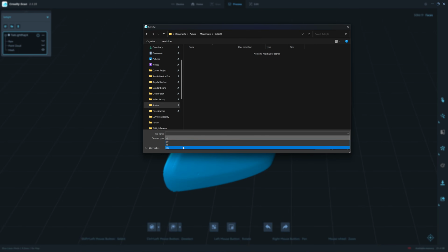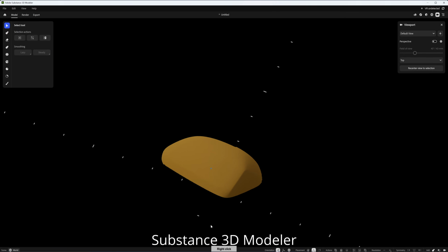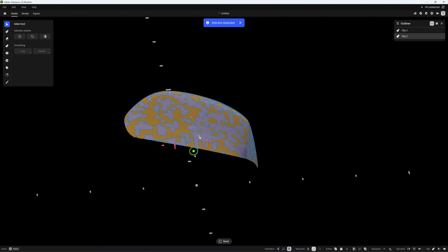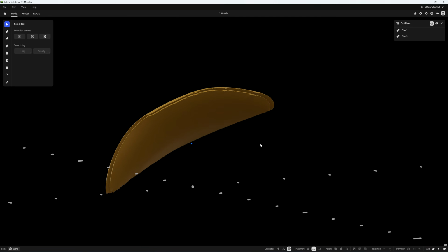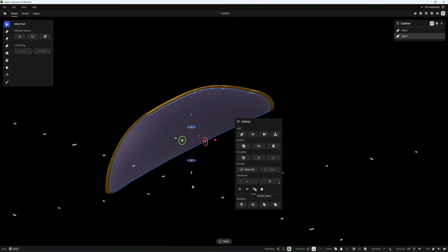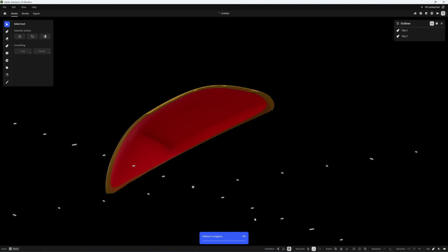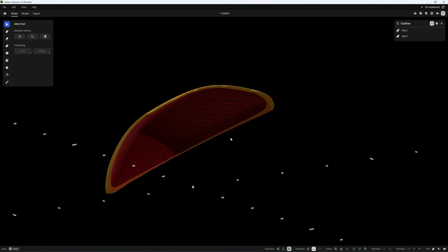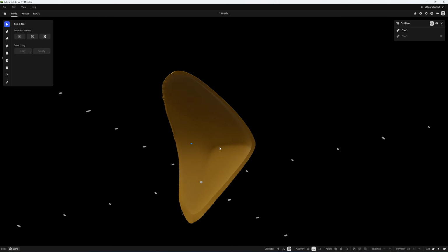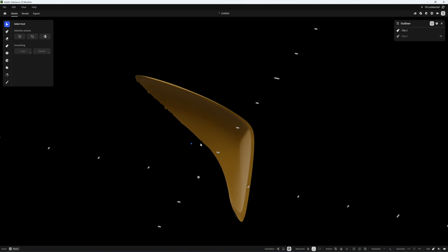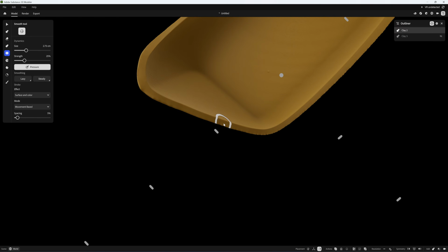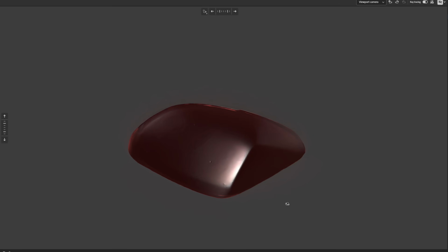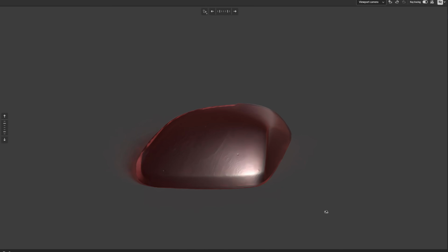And if I just want to 3D print the tail light, I will export as an OBJ file and do the modification in Adobe Substance 3D Modeler. I copy a part and make it a little bit smaller, and I use this clone part to subtract from the original part, and this will create a shell thickness because I only scanned the outside of the shell. So this tail light has no thickness, but if I do the subtraction with a smaller clone of the body, then I can get the thickness of the shell like this, and this will take only 1 minute to do, and then I can export this model for 3D printing. But this is not a CAD format, so with a bit of smoothing work, I can get the shell of the tail light with the thickness.